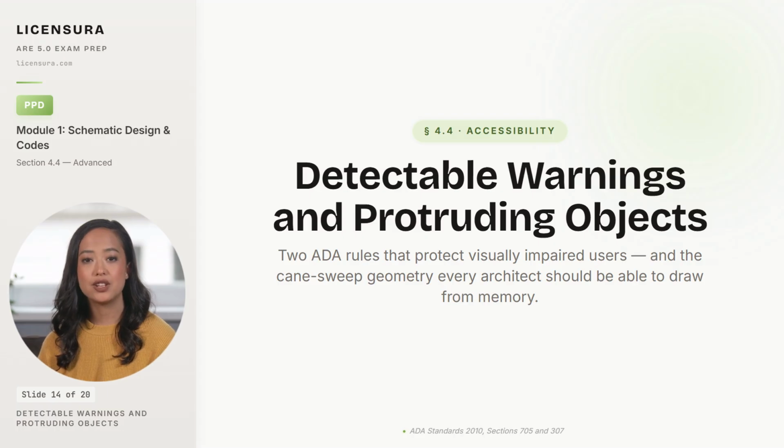Most architects can describe a curb ramp's truncated dome surface, and you have probably specified them on a streetscape detail without thinking too hard about where they are required and where they are not. The 2 ADA rules that govern visual impairment hazards are Section 705 for detectable warnings and Section 307 for protruding objects. And both turn on the same geometry: the standard long cane sweep at 27 inches above the finished floor.